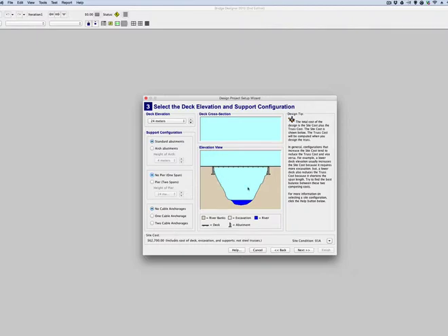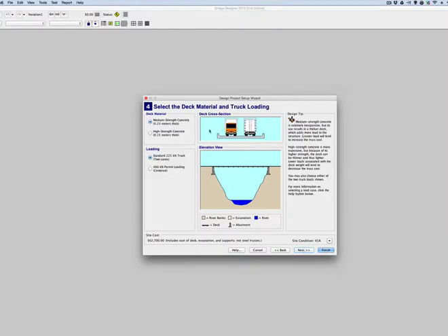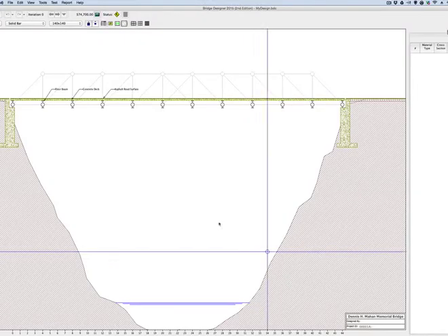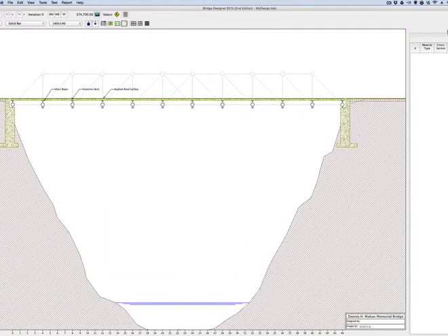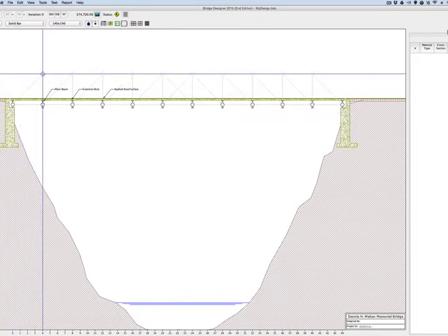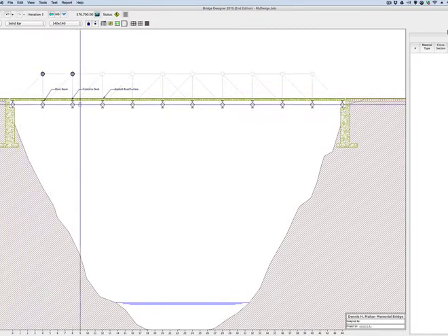Then you got cable stayed anchorages. In the beginning, leave that all just the same. Medium size concrete again, leave that be. And then do a Howe truss. Hit finish. And so what's going to happen is you have this. You don't have to worry about your joint tool. The joints are already there. So down there, they're already set.